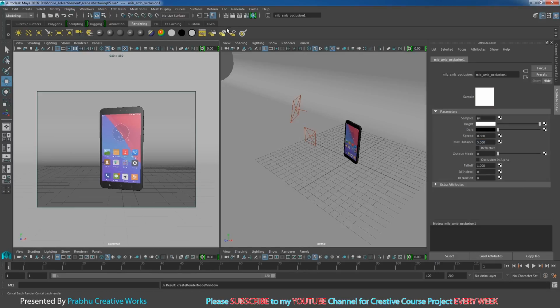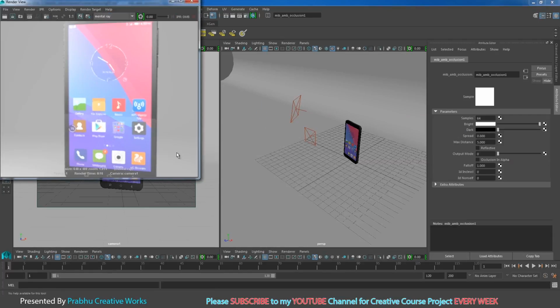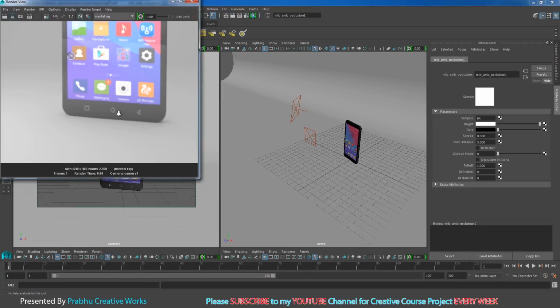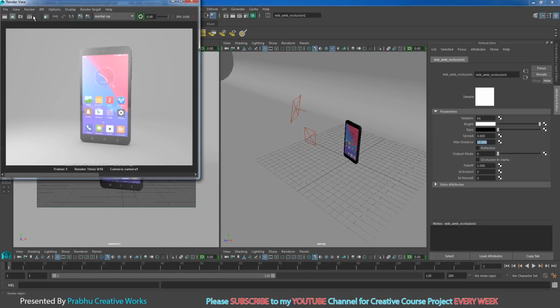I will click over here and click render. Now you see, I will zoom in a little bit. Now you see the contact shadow is available in this area. So this is what we expect. Before that, I want to increase my maximum distance to 10. I will keep this image for comparison. Click this one for comparison and click render again. Now you see our darkness has increased a little bit for our mobile.